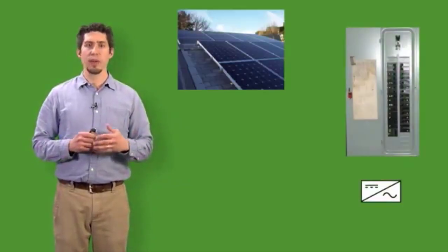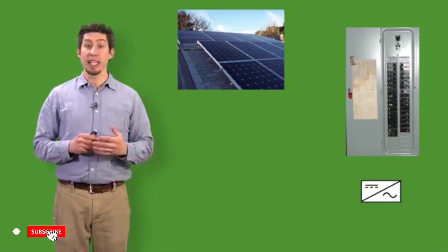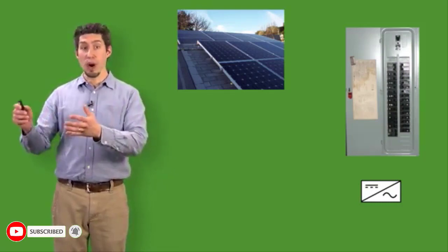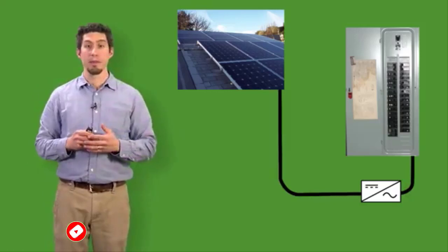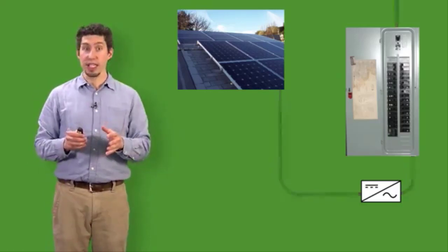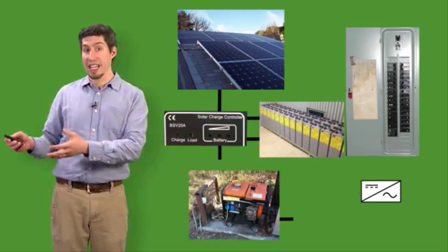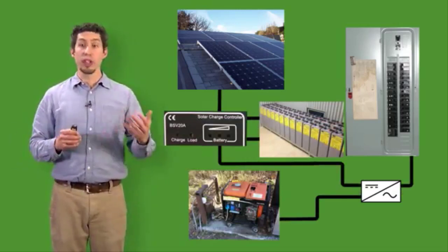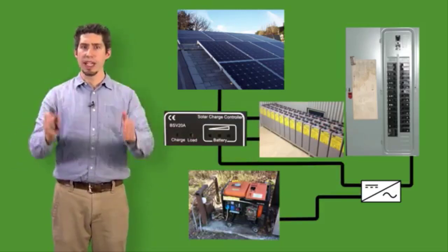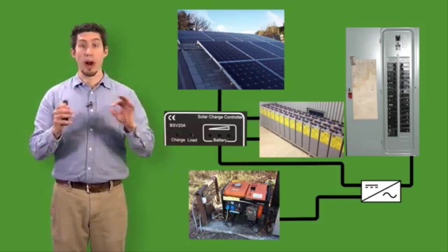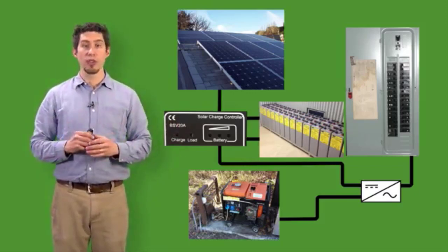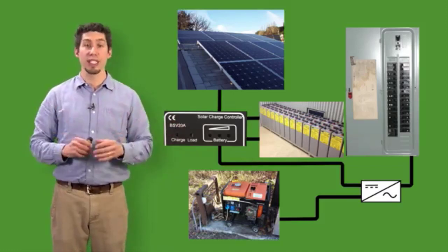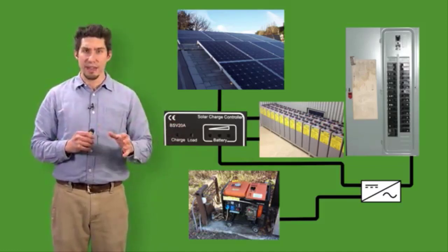The next piece of the electrical system is a building's electrical panel and the wiring infrastructure. Photovoltaics integrate with existing distribution systems, meaning that a photovoltaic electrical input is wired directly into the electrical main panel, along with the grid connection, or in this case, of off-grid wired alongside a generator. The breaker controlling the photovoltaic system is generally within the main electrical panel, so there's no need to rewire the electrical system. There are several electrical code requirements detailing how photovoltaic systems are electrically integrated safely into buildings.